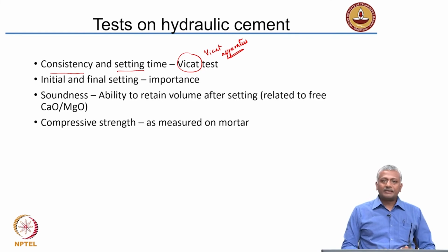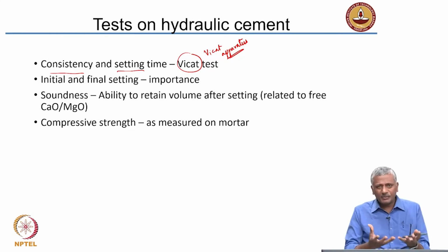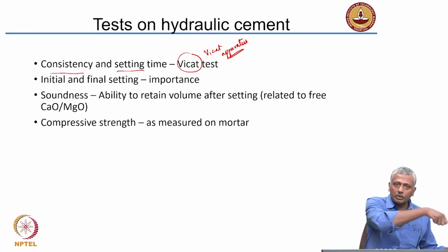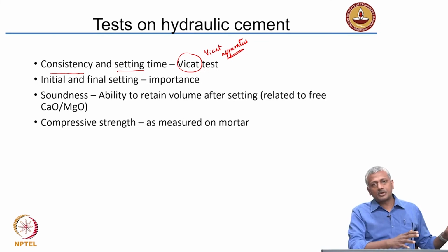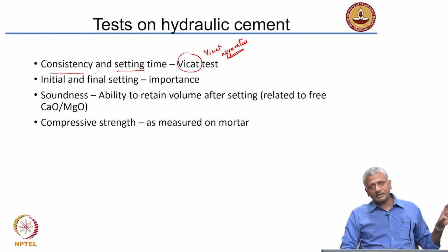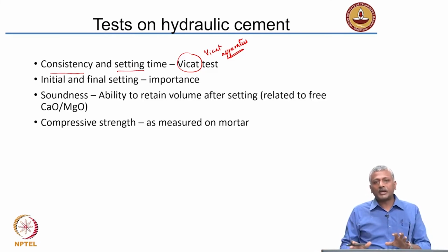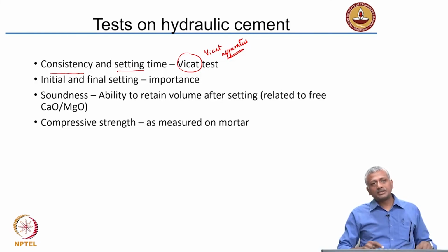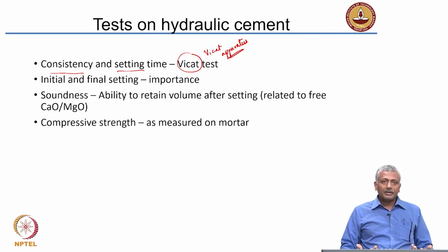Now, you know that when the concrete is first prepared by mixing water into it, cement and water come into contact, and the concrete is still very fluid. You have some time with which this concrete can be taken and put into the formwork and then consolidated and finished on the top surface. So, there is some amount of time that you get to actually complete all the operations. After you place it in position, it slowly starts stiffening and gaining strength. Beyond that point, you will not be able to rework the concrete.